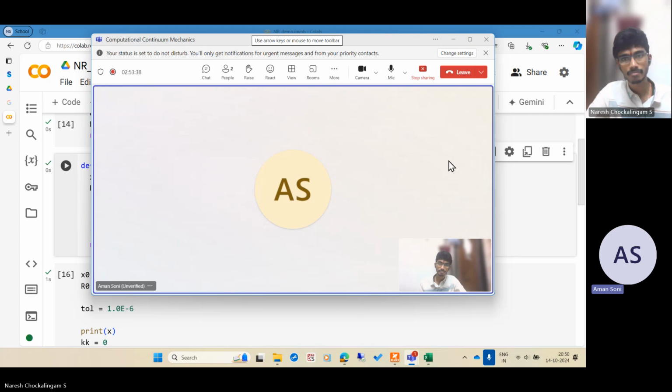In a particular area, there are some linear contacts and there are some non-linear contacts also, and those non-linear contacts are in a very small area. So there the order of non-linearity will be very large for that particular situation. And to do some approximations, I have always seen that Abaqus CAE has tried to do some iterations to get the value of the variables on the basis of the convergence criteria.